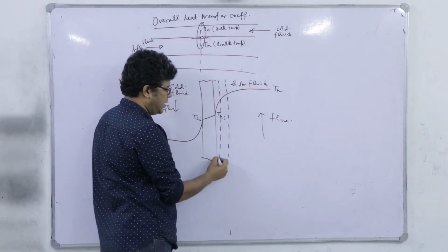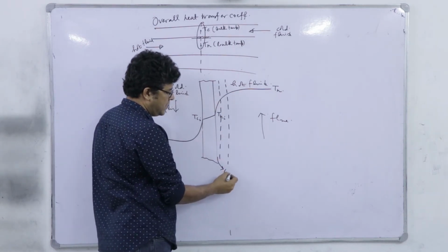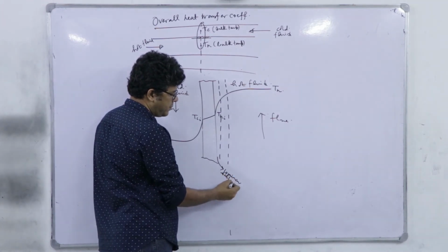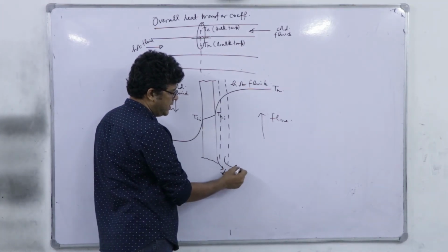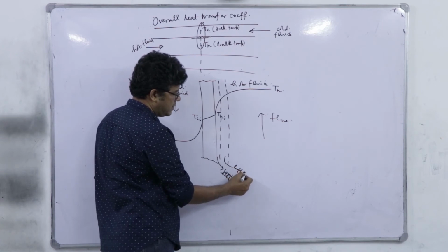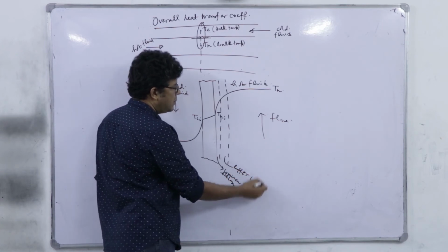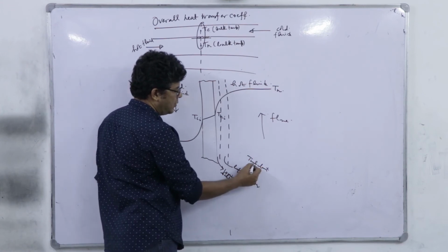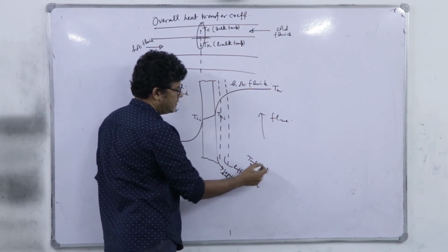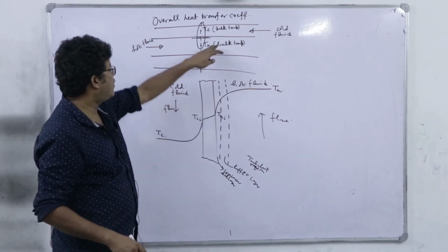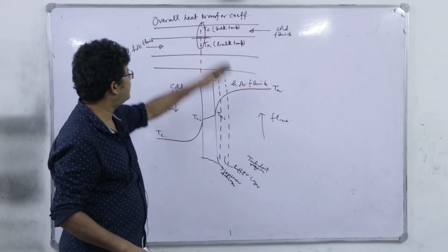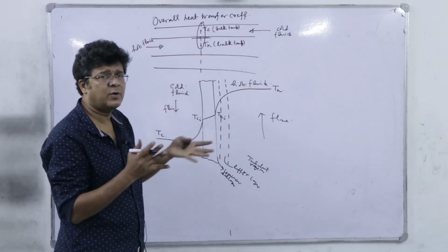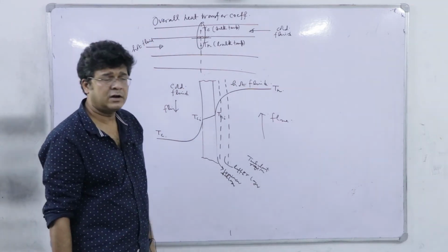If I think turbulent flow, this is the laminar sublayer, this is the buffer layer, and this is the turbulent core or turbulent region rather. We should not say it's core, because for hot fluid, okay, it's fine, it's pipe flow, but for cold fluid there is actually the core, meaning it's more associated with circular cross sectional area.